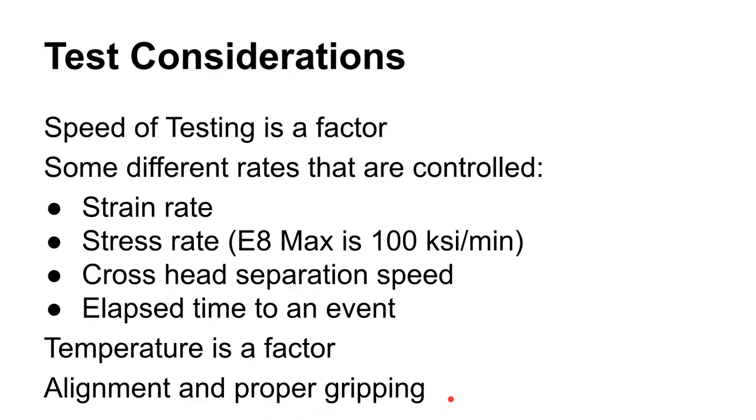If you get the part in there misaligned, you might get a reading that indicates that the part is either stronger or not as strong as it truly is. So you want to make sure that everything is set up properly.